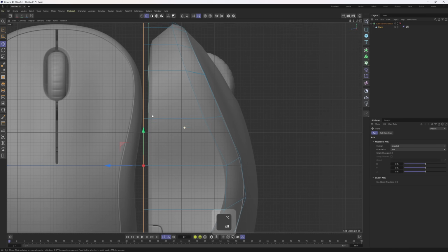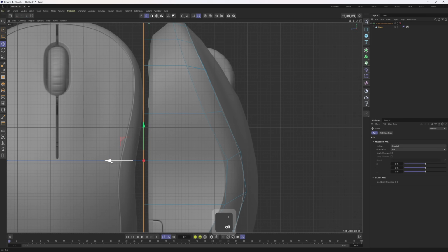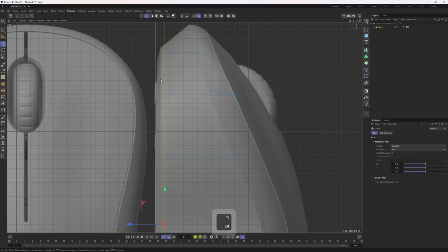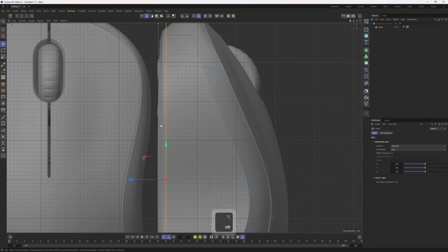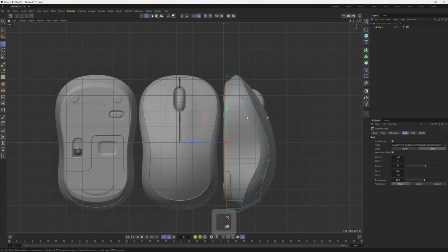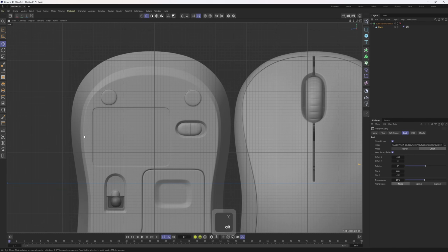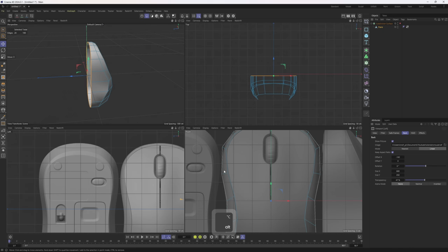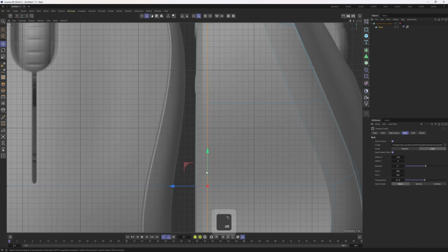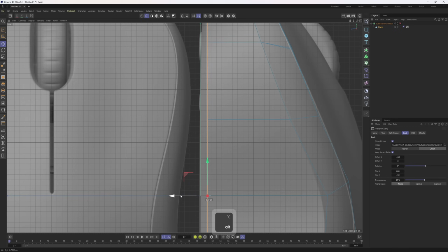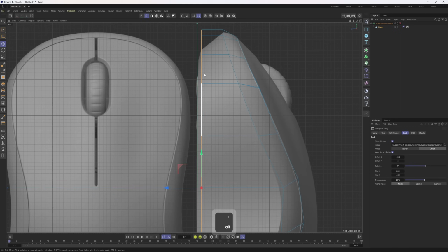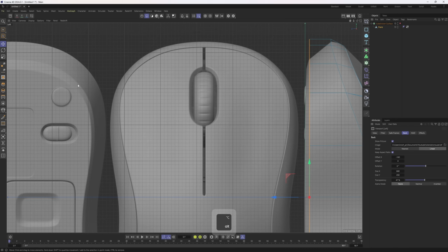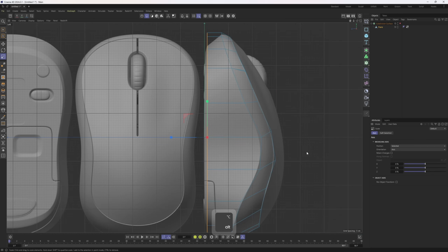And yeah, for positioning these edges, there is a bevel happening here. It might be hard to see, but you see these sharp edges. You need to work on them. So first, let me move these edges right over here, the starting point of that bevel. I will hit T and scale these in.